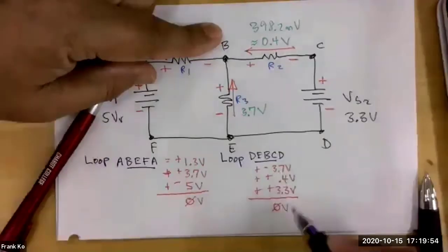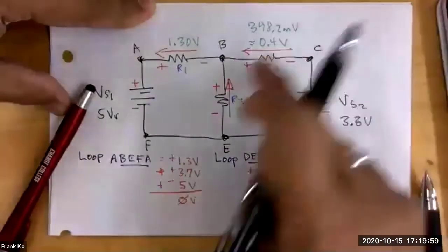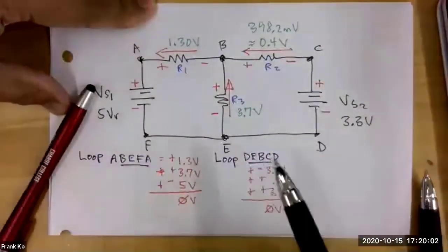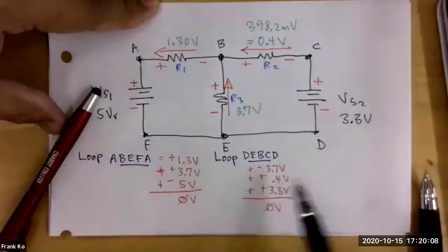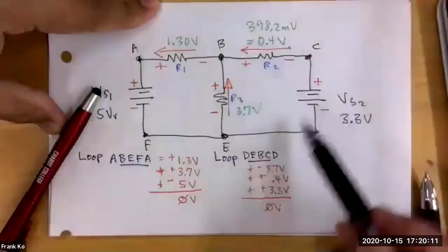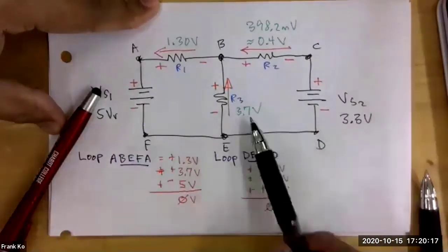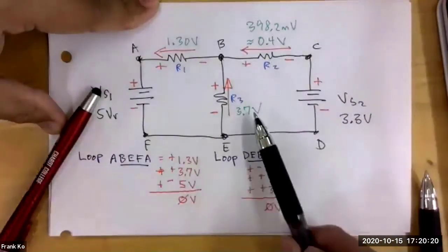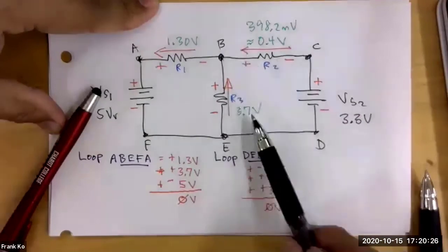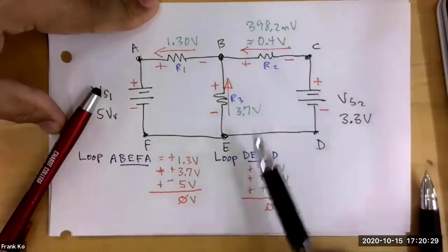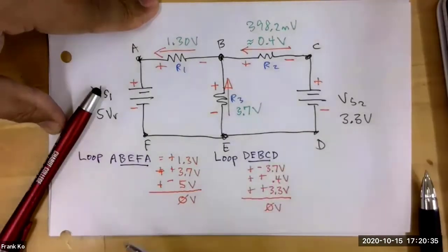Wow. Is Mr. Kirchhoff happy? Are you happy? He's not rolling around in his grave. We've got a second loop here, and yes, you've proven by using Kirchhoff's voltage law and this loop analysis that all the voltages in any closed loop algebraically must add up to 0 if the polarities are correct and if the values of the voltages are correct. Well, guess what? Your polarities are correct because they were guided by the directions of your arrows, and the values of the voltages were correct because of your analysis. So we're happy. Wei Ji, can you see another loop?